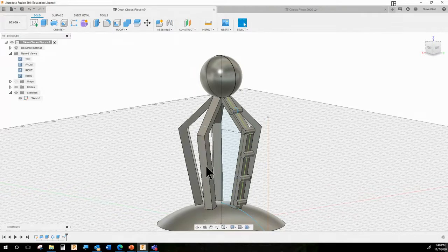Now the problem here is that I created my circular pattern here in the timeline. And I mistakenly, on purpose, created my knobby things further on in the timeline. I could have inserted that step before the circular pattern, which I'll show you how to do in a minute, but I didn't know how to do that yet, let's pretend, and I made a mistake. And I can't push these around. So what I'm going to have to do in this case is either redo this pattern on path back here, or just get rid of the circular pattern and redo it.